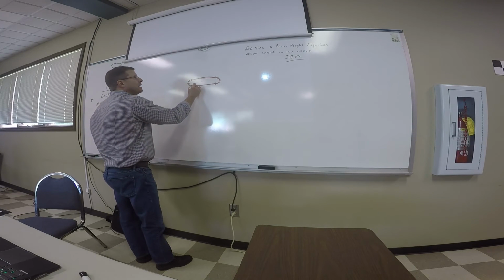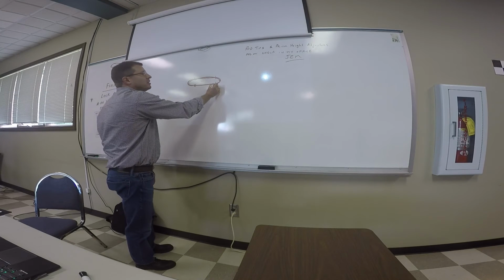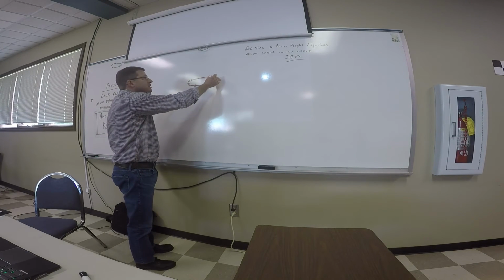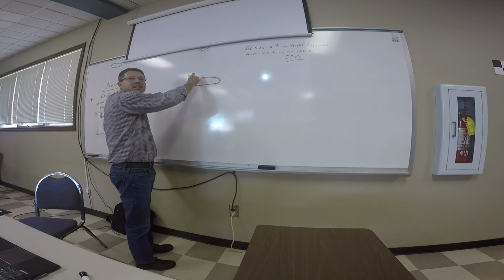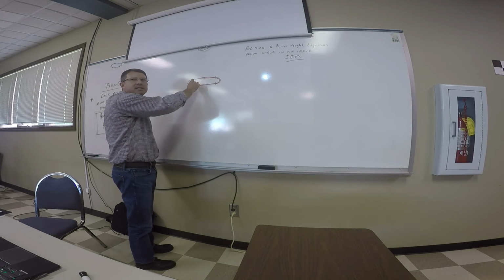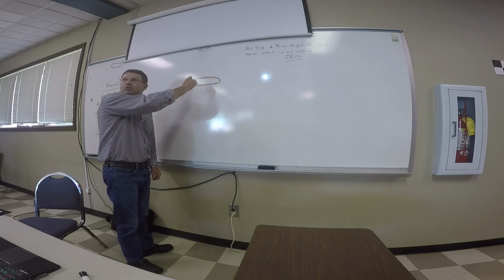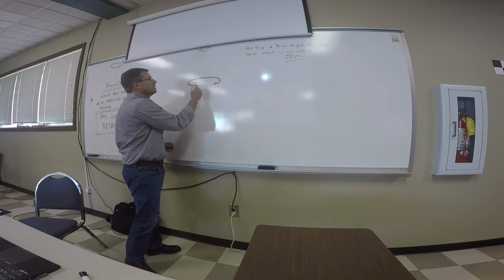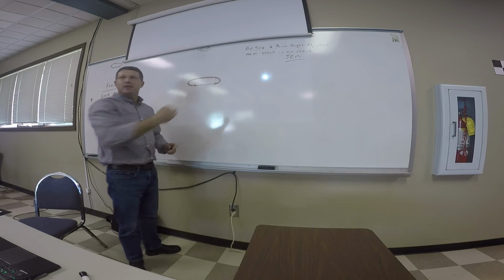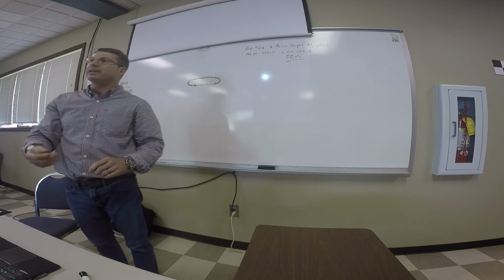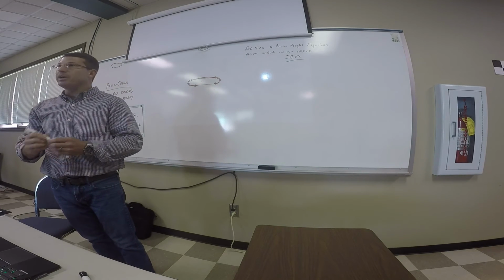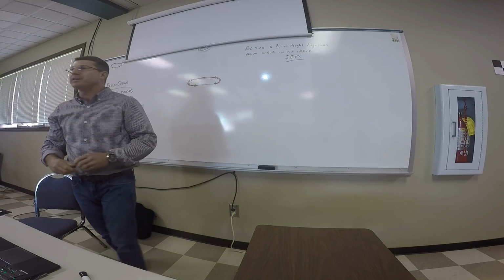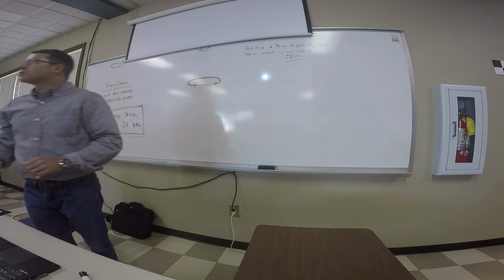On this code right here, say you start it here: gutter line 1 space PC, gutter line 1 space PT, gutter line 1 space PC, gutter line 1 space PT, space CLO. What does that do? Closes it. It draws that right there and connects that back to there. We get a 3D barrier line, and we get the 2D line that we use to offset. So it gives us 2 different lines in our field to finish. You did that with 4 shots.